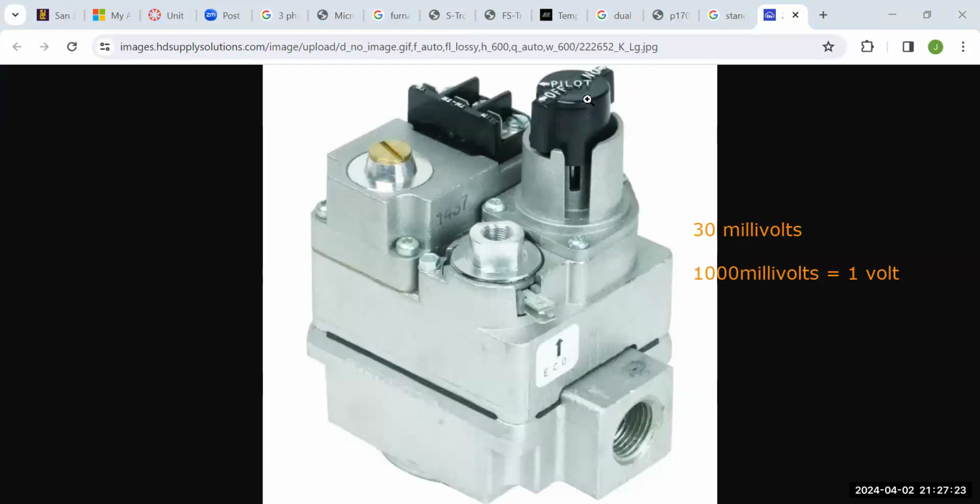So when you go to light a water heater, the first thing you need to do is turn the gas valve off. You have to make sure there's no residual gas in that water heater. If you pull the cover to get down by the pilot and it smells like gas, don't light it. You're going to have a big delayed ignition. That flame's going to come out after you. So the first thing you want to do is turn it off. Let the gas dissipate out of the furnace or out of the water heater.